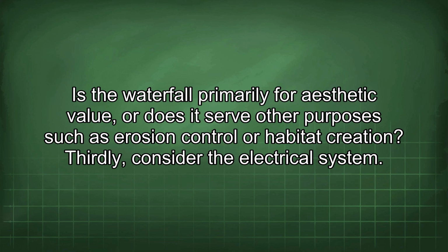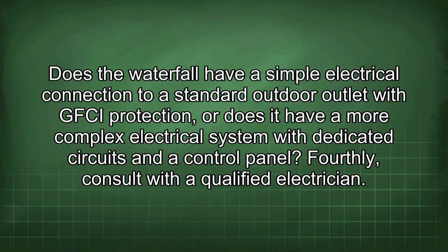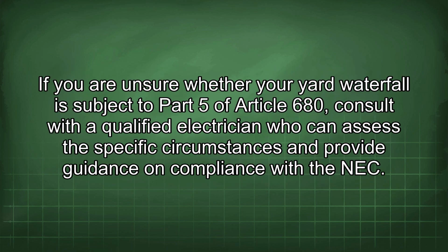Thirdly, consider the electrical system. Does the waterfall have a simple electrical connection to a standard outdoor outlet with GFCI protection, or does it have a more complex electrical system with dedicated circuits and a control panel? Fourthly, consult with a qualified electrician. If you are unsure whether your yard waterfall is subject to Part 5 of Article 680, consult with a qualified electrician who can assess the specific circumstances and provide guidance on compliance with the NEC.